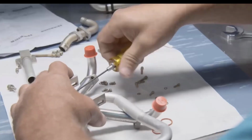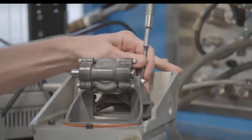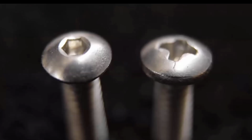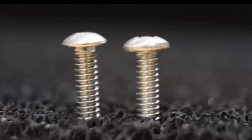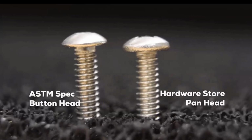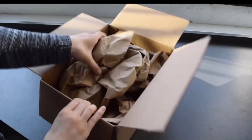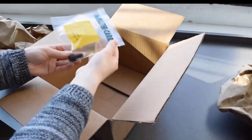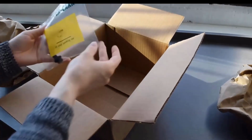It is important to ensure that the fasteners you are purchasing conform to the required specifications for your product or industry. For example, you may have seen screws like this at the hardware store, where they are typically labeled as panhead screws. Dimensionally, they are very similar to buttonhead screws, and both are made from steel and zinc plated. However, the hardware store screws are made from soft carbon steel, while the buttonheads are made from heat-treated alloy steel per an ASTM specification and are over 3 times as strong. For some projects, hardware store fasteners are fine, but for critical applications, purchase fasteners from a company like McMaster-Carr that lists exactly what specifications they conform to.